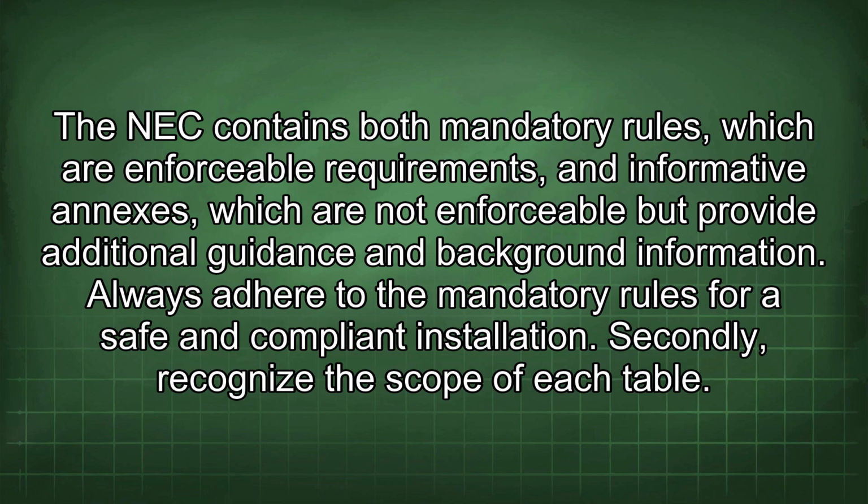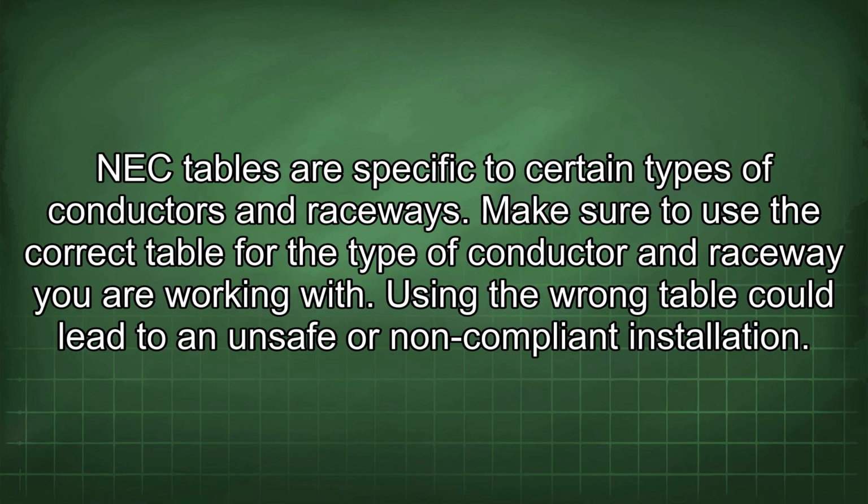Secondly, recognize the scope of each table. NEC tables are specific to certain types of conductors and raceways. Make sure to use the correct table for the type of conductor and raceway you are working with. Using the wrong table could lead to an unsafe or non-compliant installation.